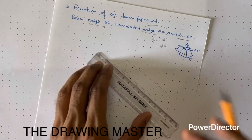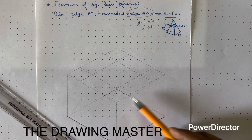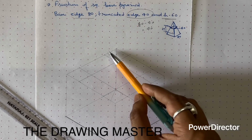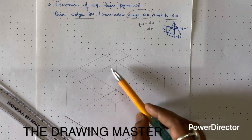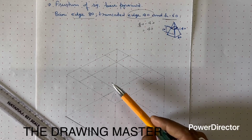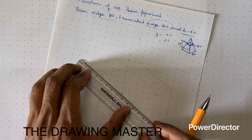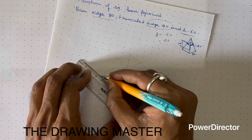So now we have subtracted 20 mm from all the sides. This was 80, but you need 40. So you have to leave 20 this side and 20 this side. Similarly, 20 this side and 20 this side. So now we got a square of 40 by 40 at the center. Square means isometric view of a square, which is a rhombus. So we'll convert this into a continuous thick line. This is the required part.